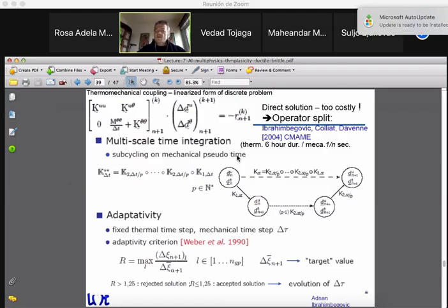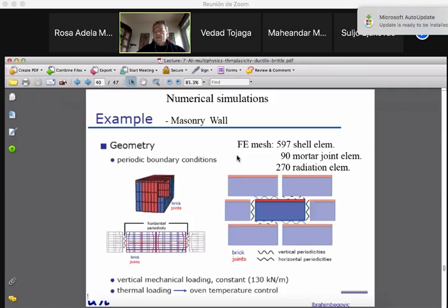If you go over a certain value, which is the chosen value of the time step for the temperature, then you go back to reduce the last one, so that you have synchronization between the value at the end for temperature, the value at n plus one for the temperature. So basically, you have a really very large temperature time step and smaller mechanics steps, so you can run it. And this is actually what is giving us all these really good results.